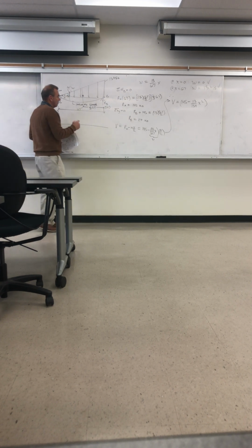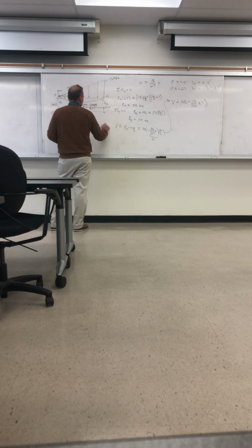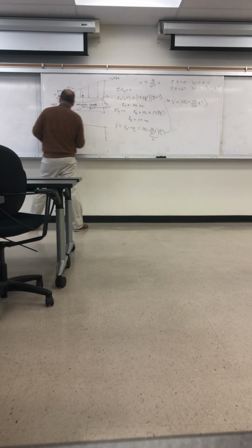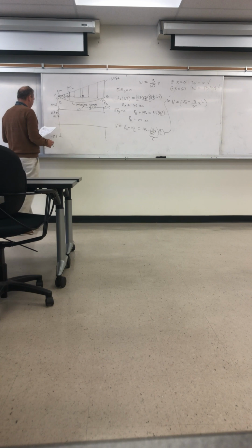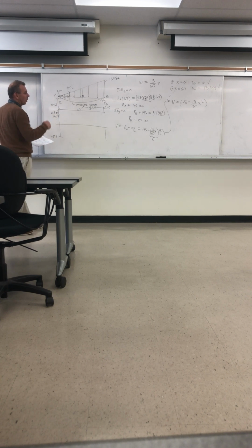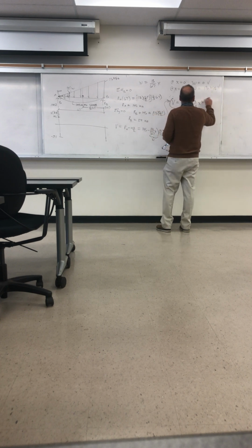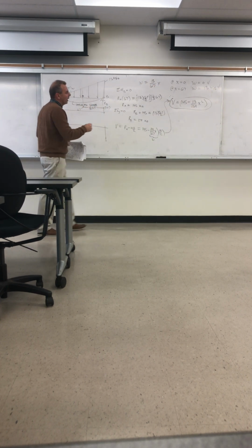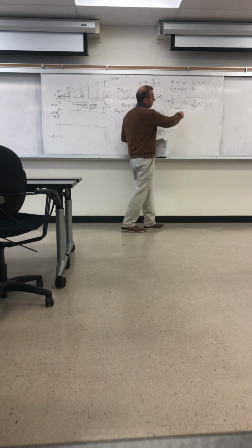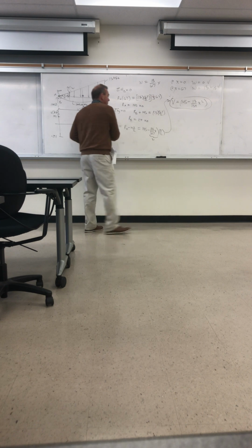For the same reasons given before, our definition of positive shear. So here we have minus 291. And then because of that square term, looking at this expression, it's 145 minus that. If we put in x here of 67, we get back minus the 291.